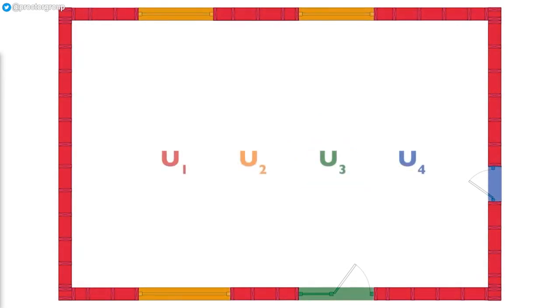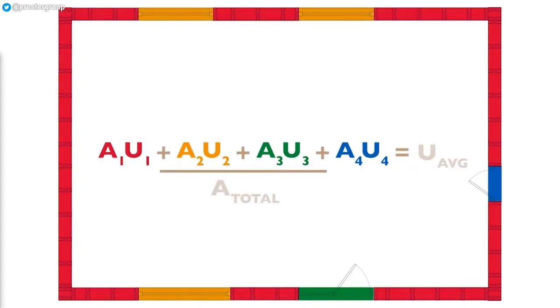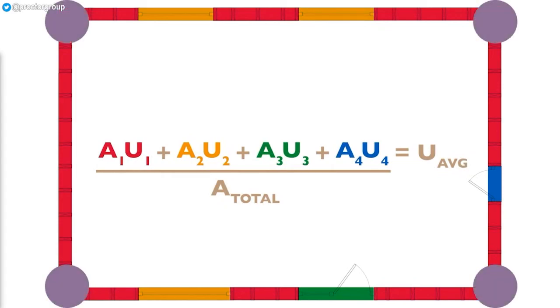The next step is to take all our U values for walls, doors, windows, roofs, and whatever other elements we have in our thermal envelope design, weight them by their respective area, and derive an overall average U value for the entire building. We can then adjust that to account for non-repeating thermal bridges like corner junctions, floor zones, etc., and end up with our complete heat loss model.